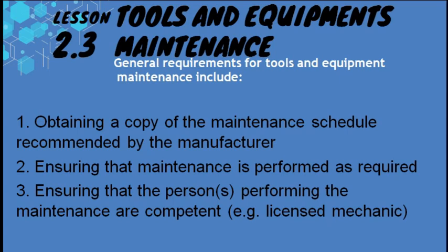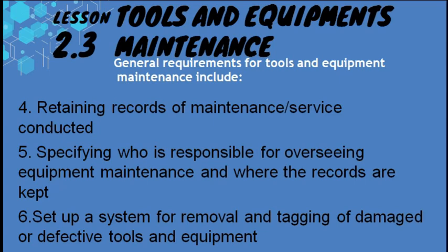3. Ensuring that the persons performing the maintenance are competent or licensed mechanics. 4. Retaining records of maintenance or service conducted. 5. Specifying who is responsible for overseeing equipment maintenance, and where the records are kept. 6. Setting up a system for removal and tagging of damaged or defective tools and equipment.